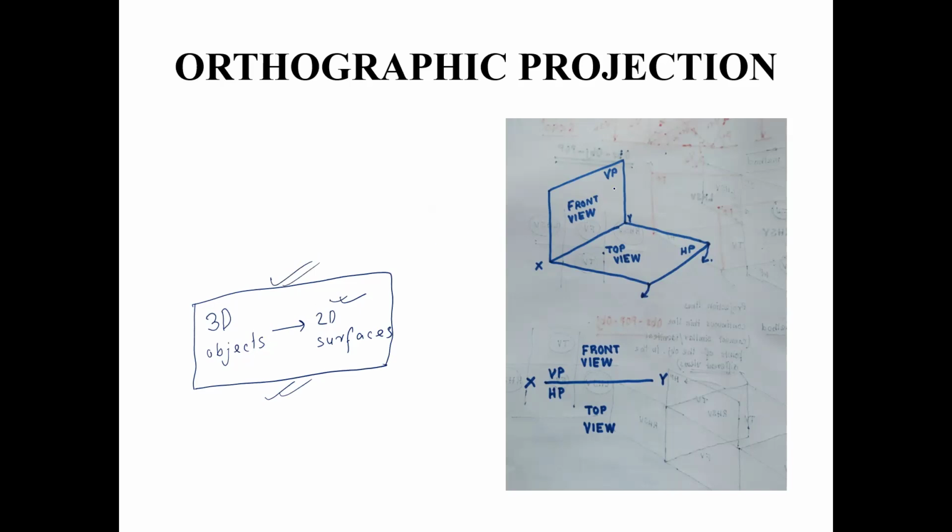Here we can see two planes of projection out of the three. We can understand this concept using two planes of projection, and using three planes of projection also. But for the sake of simplicity, in this slide, I have included only two planes of projection. Look at their names. We have the vertical plane of projection, so the front view of the object will be captured on this plane.